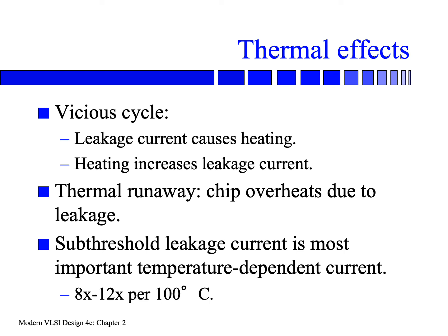Also, in some situations we could have so-called thermal runaway. Thermal runaway means that if you increase temperature, the leakage will increase. Leakage increase leads to higher temperature, and high temperature leads to more leakage increase. So you end up with this positive feedback, and eventually the chip will shut down, totally break.